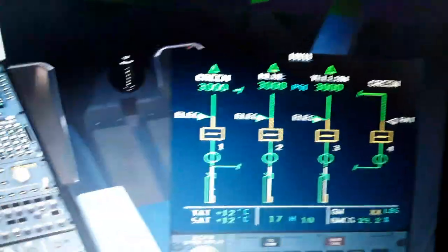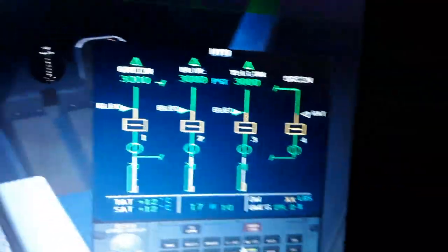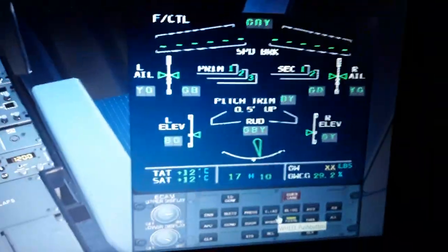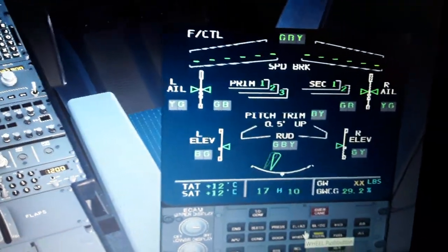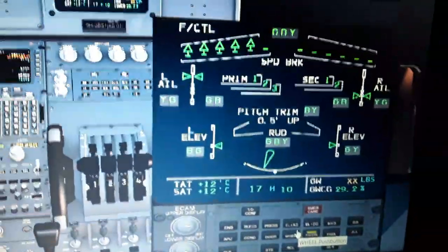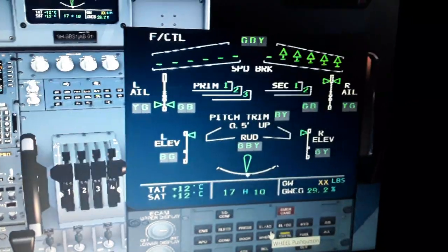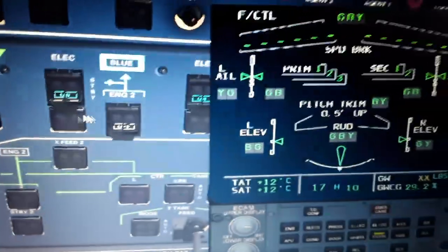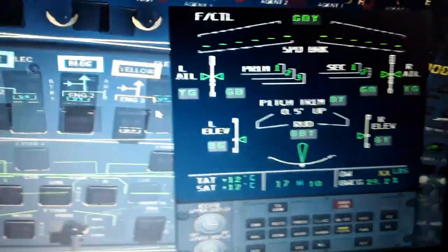So we have back the standby flight controls. You can see the rudder is moving, the rudder pedals. We move the rudder. We also have the electrical pitch trim here, and the ailerons and the spoilers. And the elevator is moving. So we can use this configuration instead of the engines, but we reconnect the engines to hydraulic pumps.